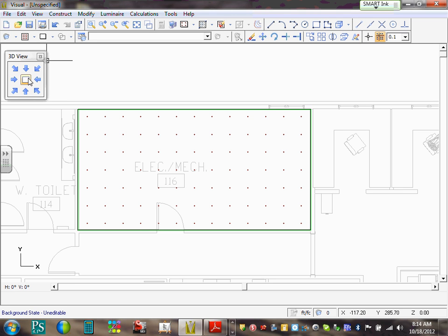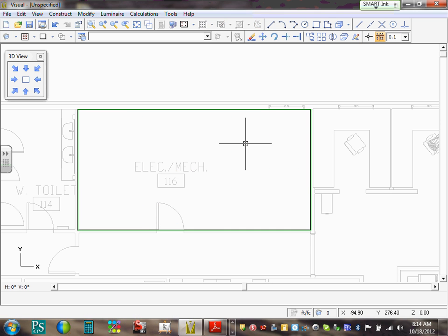Everybody go to the plan view. Do you see what I see here? Oh, when I clicked, it didn't do it. It didn't put the dots on there. It did not? Okay. You made a mistake, right? No problem. Here's what you need to do. I'm just going to go erase. Made a mistake, right? I'm going to hit erase. If you go right to left, anything you touch, it will pick. So I pick it like this, hit erase and right click. Now I erased it. Made a mistake. Go back, do it again.